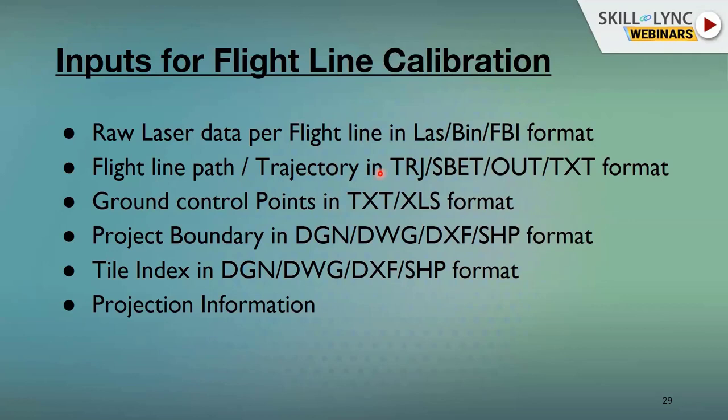The mediator is the timestamp. If you lose your timestamps in the LiDAR data, you cannot use the LiDAR data. If you lose any timestamp value in the trajectory, you cannot do any further process, like data calibration, data classification, and generating the outputs.